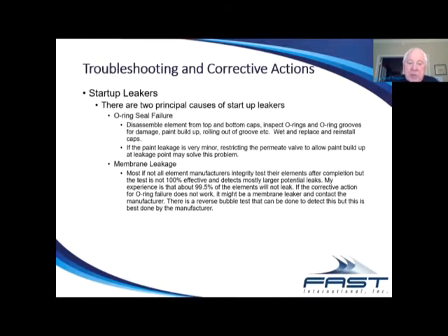My experience is that, at that time, it was PTI Advanced Filtration, the old AMT product line. When we took it over, they had about a 3% leakage rate in the field. By doing a better job of it, we got it down, not perfect, but to around 0.5% leakage. And first thing, of course, you do is do the corrective action for the O-ring failure.